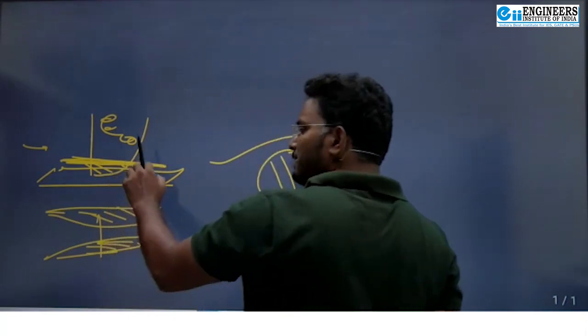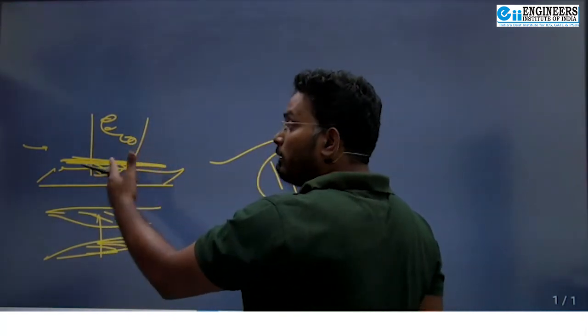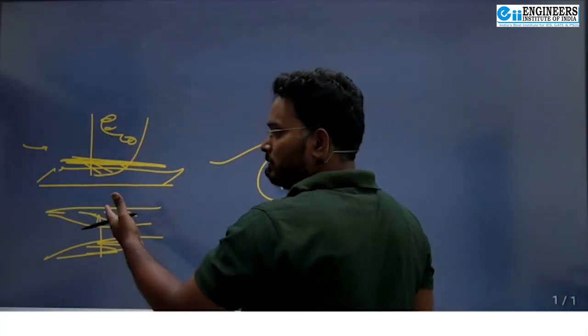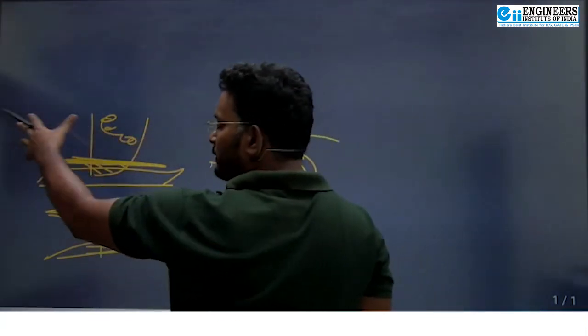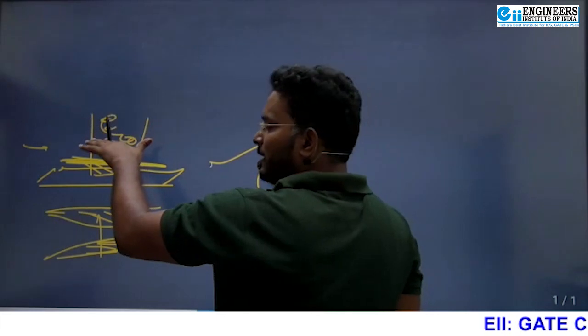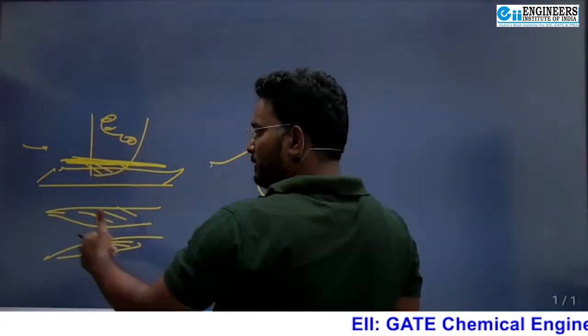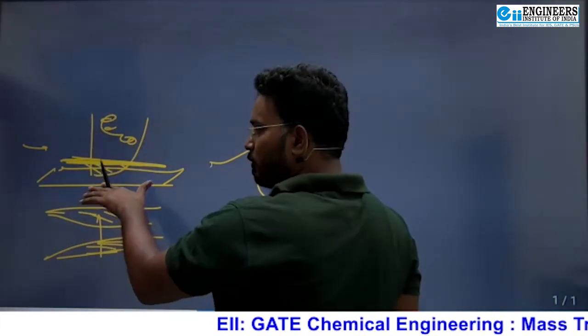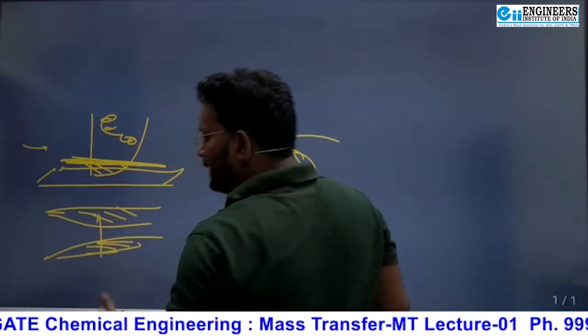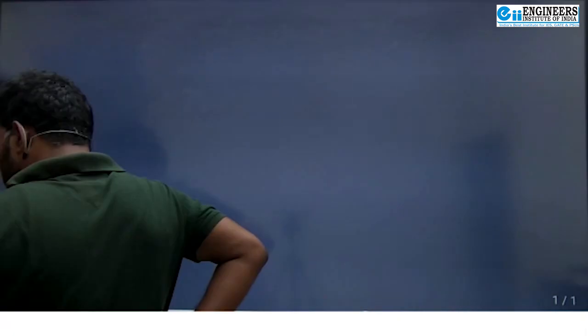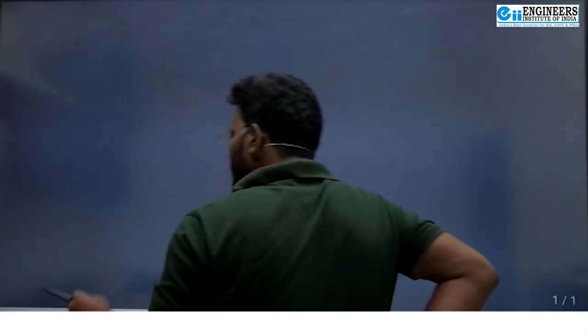In the viscous sublayer, any transport is dominated only by molecular properties, called molecular diffusion. So even though the bulk flow is turbulent, the mass transfer close to the boundary, close to the solid surface, is going to be dominated by molecular diffusion as compared to eddy diffusion. Clear? Now in general, what I can write here, listen,